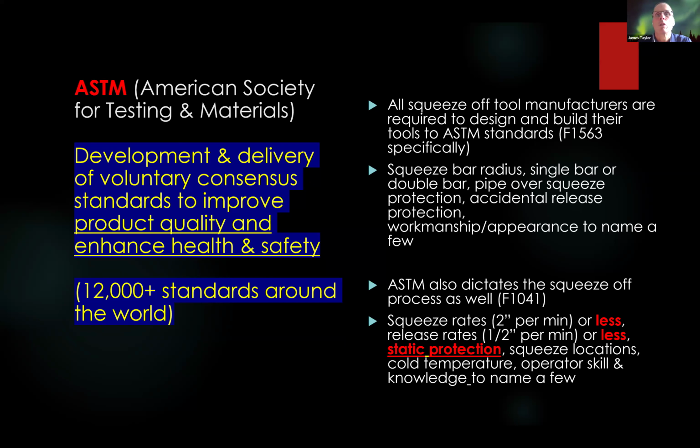For the static protection in 1041, everything has to be statically grounded. I'm stealing too much of Dirk's thunder, but everything has to be grounded. That's why his product and our static ground spike we have with our tool work hand in hand as a safety feature. There's also the Plastic Pipe Institute, which has their technical note TN-54, and they say double squeeze and release times in cold weather. So it's two big organizations that know that data, that safety information that's been tested and true.